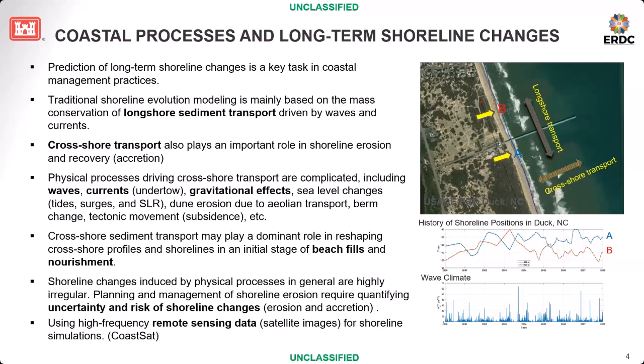The good thing is the current GenCade can take into account current, sea level rise, and gravity effects on slope. With those challenges from practical application and engineering practice, we also try our best to provide a capability like Monte Carlo simulation to estimate the uncertainties and risks of shoreline change.